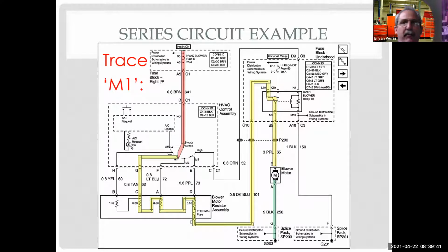So you're right. We'd have system voltage there because I can't use any voltage through here because I effectively don't have a load there because it's not a complete circuit. And this is the reason why I bring this up: people get confused a lot when they're testing this. Gee, I turned it to B and I got battery power at B and less than battery power over here. But then when I go to C, these both have battery power. When I go to A, all three of these have battery power. If I go to D, all four have battery power. I think the switch is shorted.